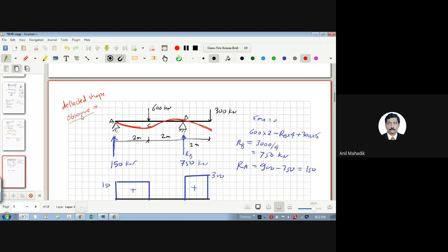You can visually see the deflections, because as far as beams are concerned, they are generally RCC or steel, and they don't deflect visibly. Internally they are deflecting like this, but the deflection values are very small, so you cannot see it through your eyes, because the members are quite stiff and the deflections are very less.